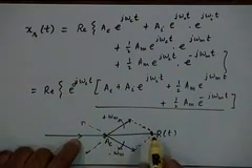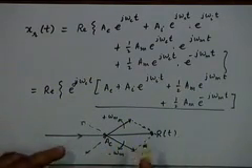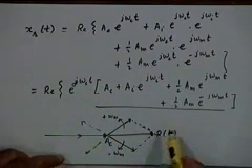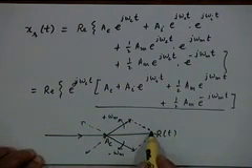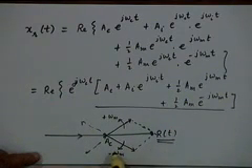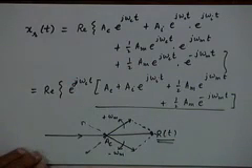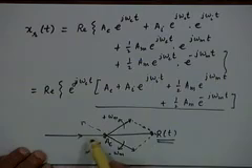So basically what you will see is that the carrier wave is being modulated in amplitude around A_c, right? It's going up and down in proportion to the message signal cosine omega mt, right? Is that clear? So that's how the whole thing is working, and the envelope detector will actually follow this. You can think of this R of t, the resultant amplitude, as the envelope. This is the envelope that you will try to trace through the envelope detector. It will be sensitive to this envelope amplitude, envelope value, right?